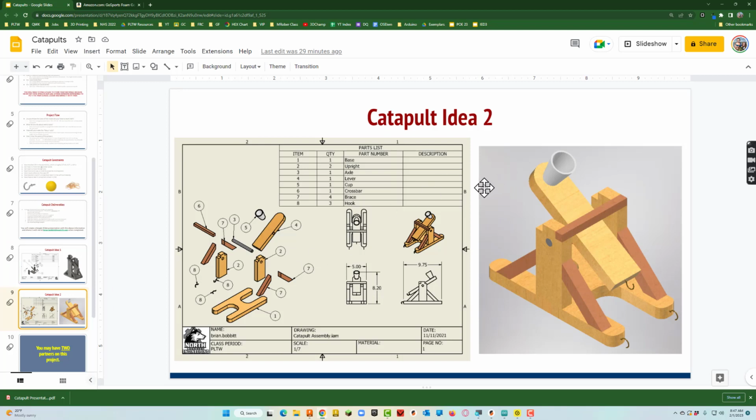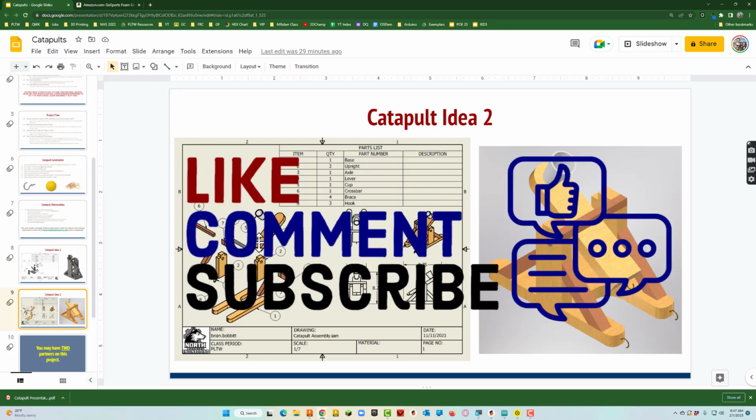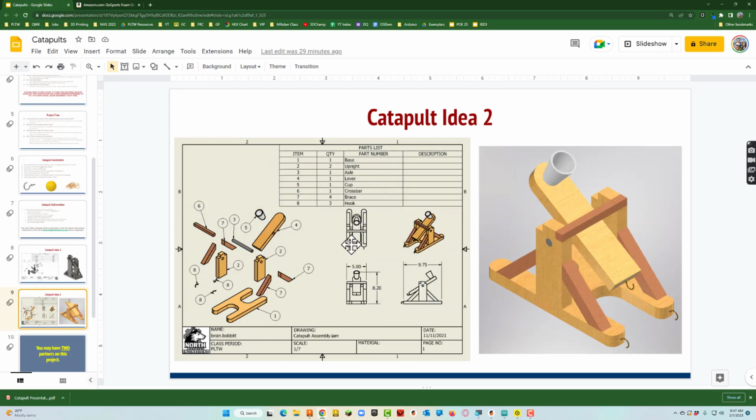This is one I actually modeled in Inventor. See, a little more complete with the exploded view, bill of materials, and then even an assembly view. And in our assembly views, all we're trying to do is, if this were a trophy, make sure it can fit in the trophy case. So that's all we're doing with the dimensioning there. So you can see that's not crazy involved.